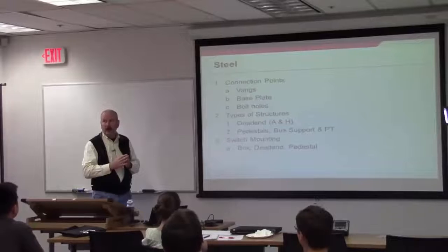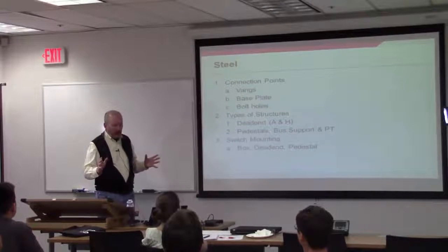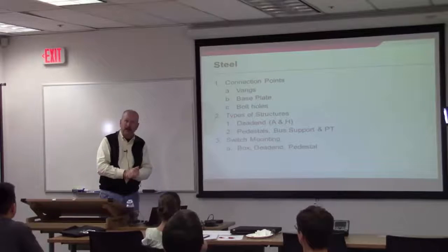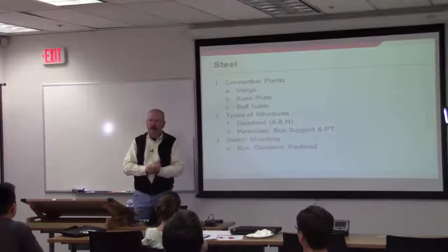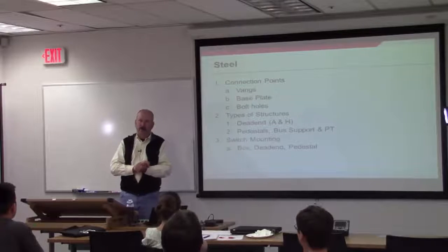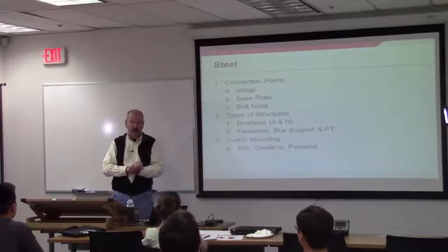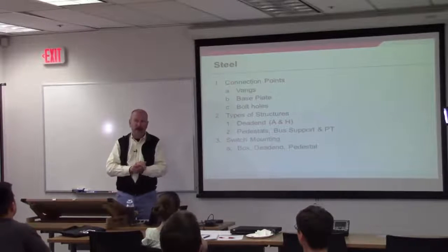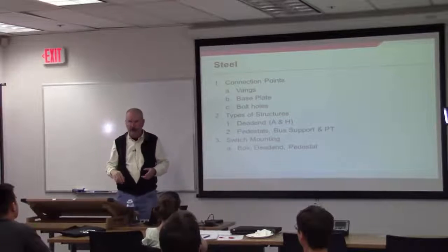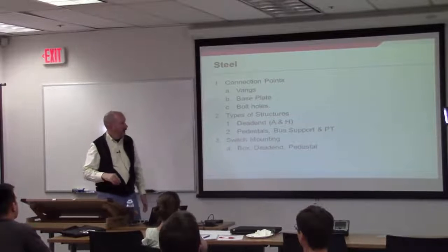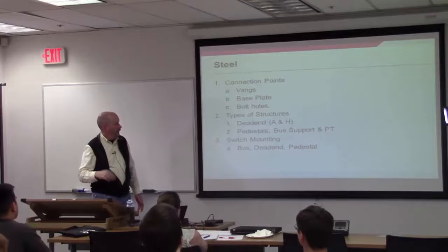We did a project out by Hag Lake, and I'll never forget it. They went to the lowest bid. They went to a new steel supplier that was the lowest bid job. And where every bolt hole was supposed to be 3/4 of an inch, they made them a little more than 1/8 of an inch small. They had to bore out every one of those in the field. It was awful. It was about a 2 to 3 week delay to the project. So again, something to keep in mind.